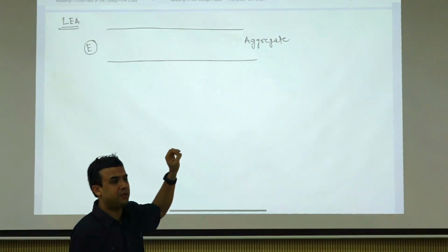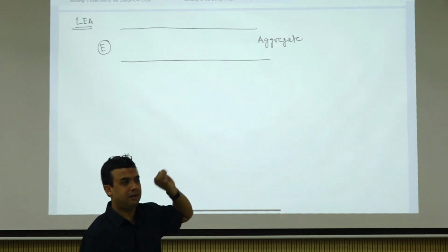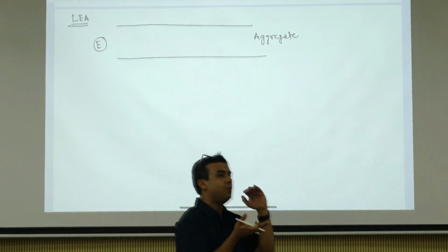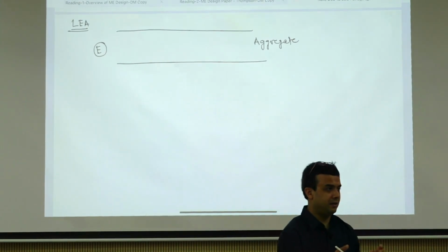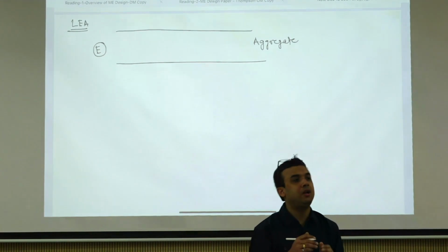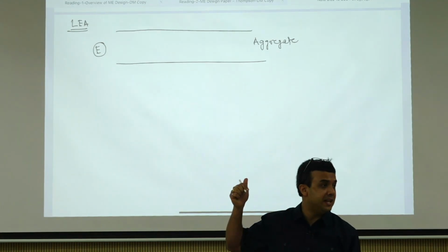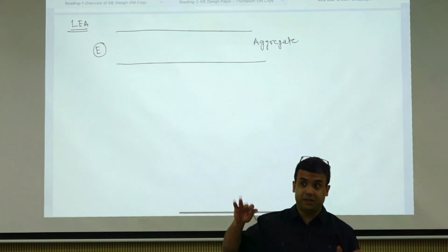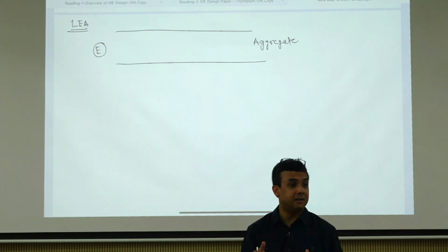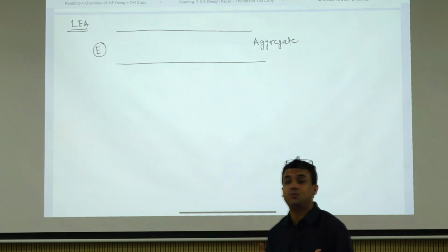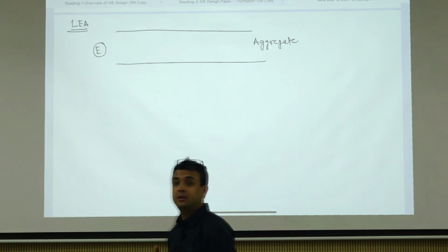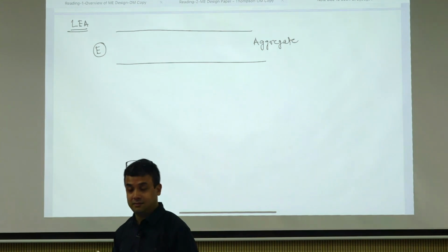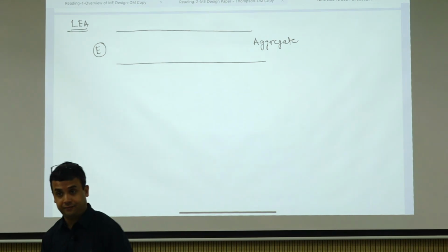Do you understand the question? The software is able to take only one modulus per layer, but you know that modulus changes within this layer. It should, right? But your software is not capable of doing that. What's your poor man's way? How can you cheat the system? You can sublayer, right?